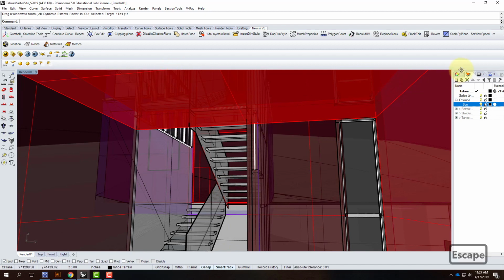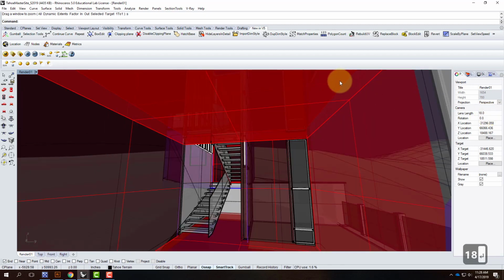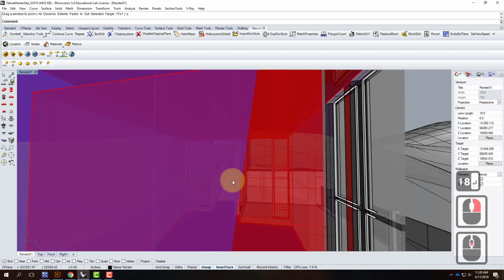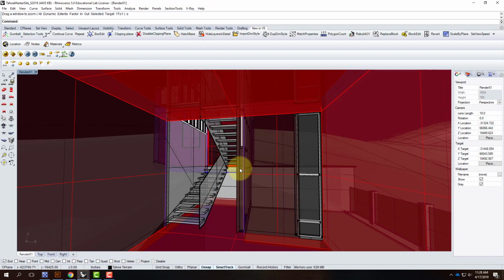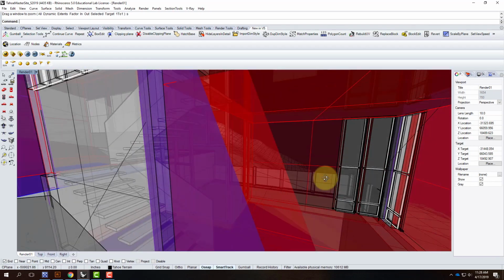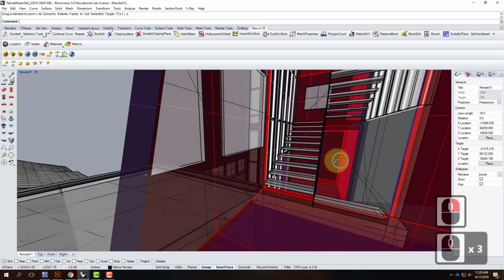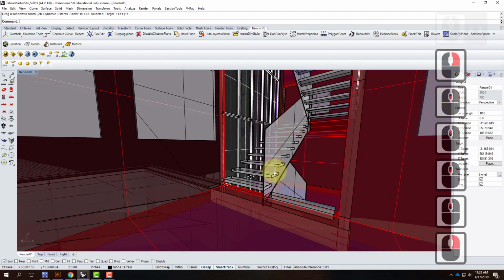Now, with nothing selected, because we're doing an interior, I might change my lens length from, in this case, I had it at 35 or maybe 28. I might change it down to 18. It's kind of like when you watch HDTV, and they always have the really wide angles when they're shooting the interiors because you can't see that much. And so in this scenario, maybe I'm happy with that view. Maybe I want to flip around and do a rendering that's back over in here. I have to sort out what is that ideal view.